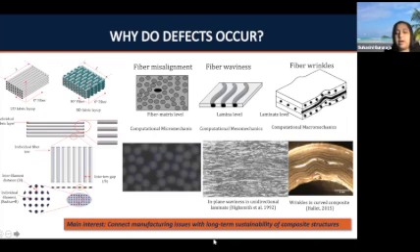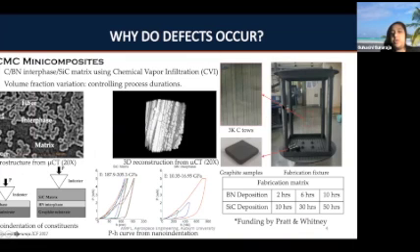So the objective of any kind of study that looks at these microstructures would be to look at the correlation between the microstructure, the process, and finally the property that you would obtain for these kinds of materials. Just to give an example, one of the projects that one of my PhD students is finishing up is on CMC mini composites. These are called mini composites because we make these materials using individual toes. These toes are kept in place while a process called chemical vapor infiltration occurs, and you end up getting a microstructure somewhat like this.